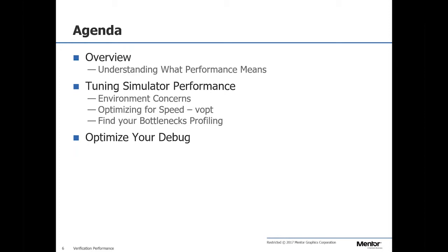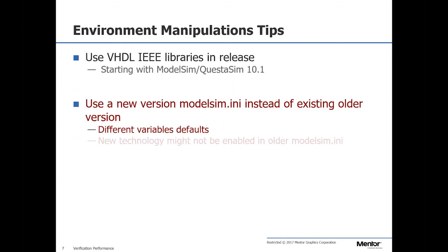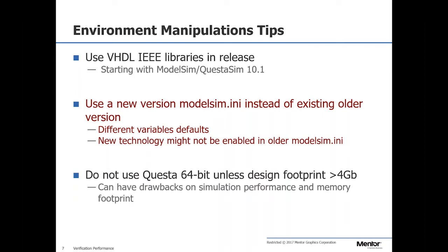So the first bit we'll do here is just talk about how to make sure you really have your fastest simulation environments. And so a couple of tips that I like to give is, I don't know how many of you do VHDL designs versus Verilog designs, but if you do use the VHDL designs and you do use the math packages, the standard arith package, the standard math package, the signed and unsigned packages, just make sure that you're referencing the official IEEE versions and not kind of the legacy Synopsys ones, because we've spent a bit of time